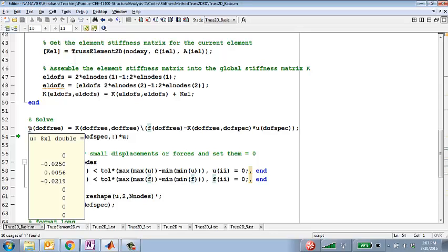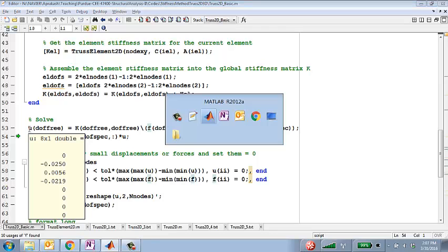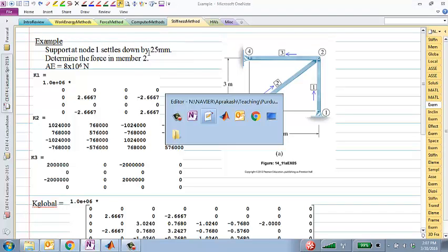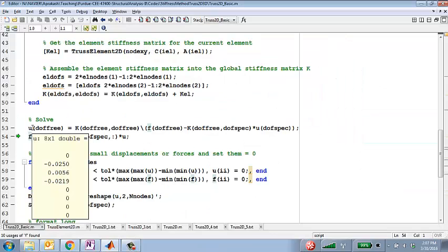Still, most of it looks zero. Why is that? Right, because the truss really has 3 supports and only 2 degrees of freedom corresponding to node 2 are free. In addition, there should be some displacement at degree of freedom 2 for node 1, which is what the problem states. So there should be 3 total non-zero displacements. And indeed, that's what we get.